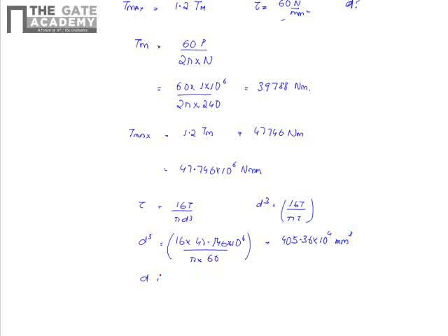Therefore, d will be cube root of that. That will become 159.4 mm. That is close to 160 mm. That is the diameter of the shaft.